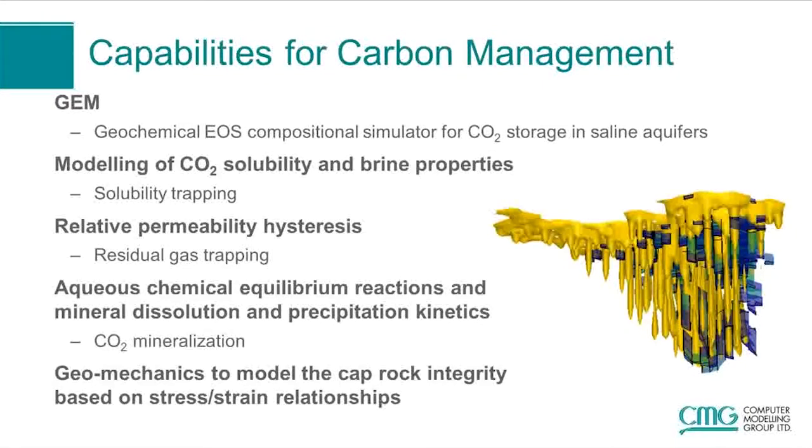In the cases that you have carbon dioxide leakage from the aquifer, you can couple the reservoir flow with the geomechanics to capture the cap rock integrity or the carbon dioxide leakage due to the change in stress in the reservoir.